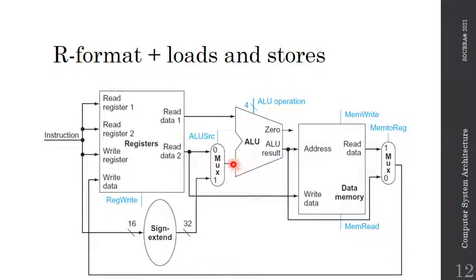And you can notice that this particular arrow is 32 bits, right? Because the ALU is expecting two inputs of 32 bits. This one for sure is 32 bits because I'm reading it from the source register. And that one for now is 32 because I've just extended it from the slide before. Fair enough?